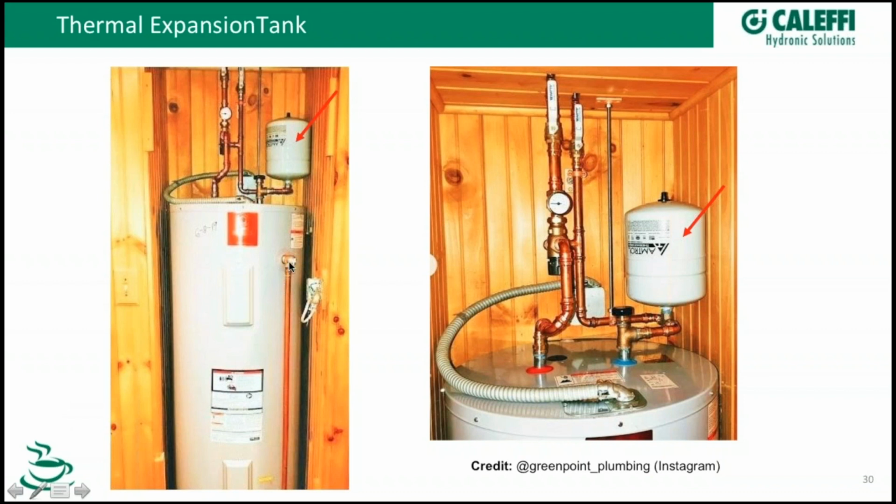What I would also caution you about on a relief valve, two other things actually, is you want to have this discharge tube put on it so that if this thing does go off someday, either on purpose or by mistake, it discharges down the floor, that it doesn't blow out on the wall. In fact, that should go down to a drain or discharge somewhere safe. I would say that it's not going to cause damage inside the building, inside the home, especially in a closet like this with all this nice woodwork around it.